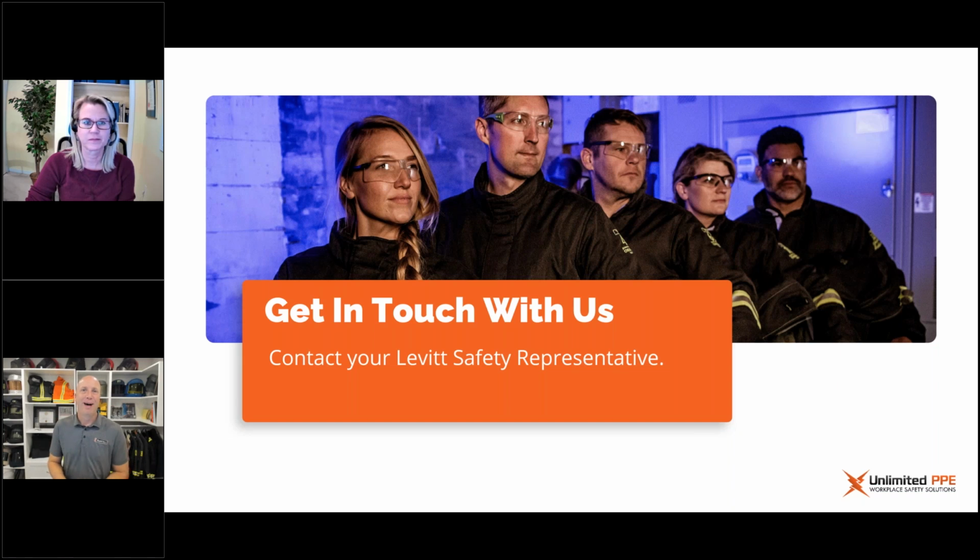They're not FR. The best ones are actually the most inexpensive, the little barrel-shaped ones where you roll them down and insert them in your ear. I think we can all rest assured that if you're wearing adequate PPE, your earplug should never be exposed to an arc flash. And if you want to wear earmuffs, because you do want the ease of an earmuff versus an insert, you have to have a hood, some way to protect that earmuff.